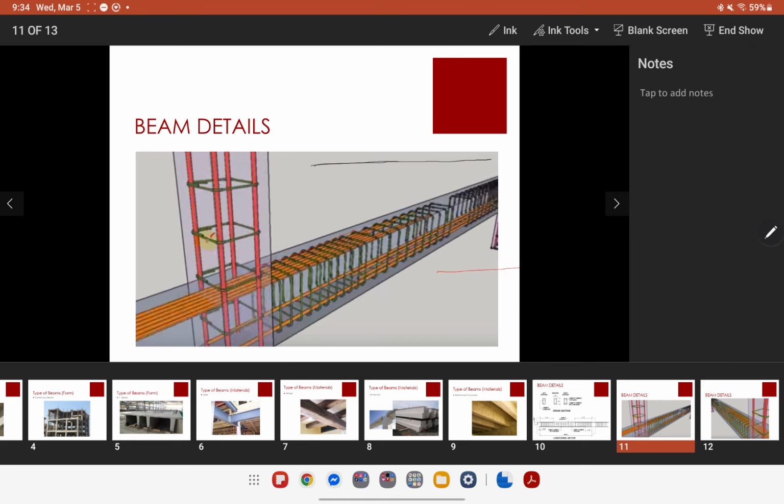So in the drawing here, this area here, the support end, the left or the right support, and also the middle part of the bottom bars will be the ones requiring more rebars, while the one in the middle will require less rebars, because again this part will be in compression, while this one will be in tension.